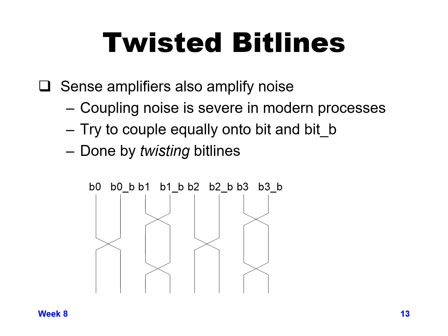Now, one final note about the bit lines and sense amplifiers is keep in mind the sense amplifiers are trying to detect a fairly small differential between bit and bit bar. And since they're trying to detect such a small differential, they do a pretty good job amplifying small differentials, which, namely, noise is something that can create a small differential.